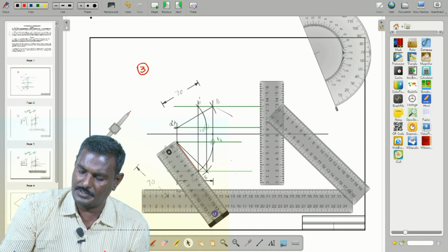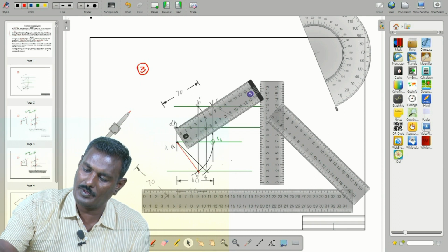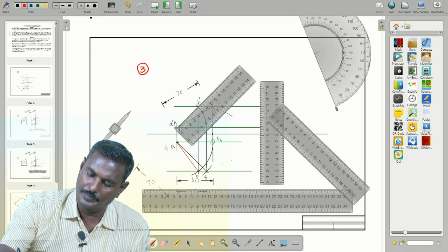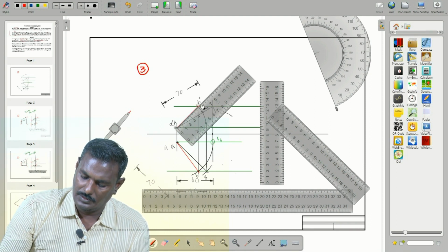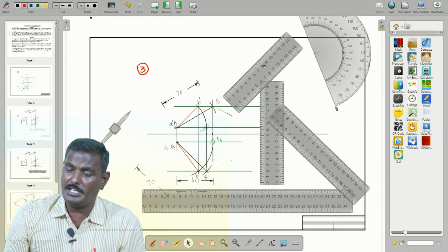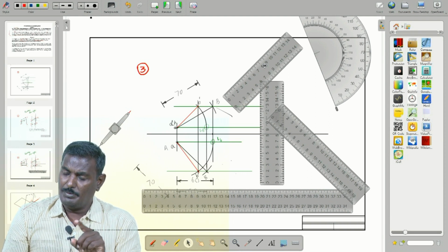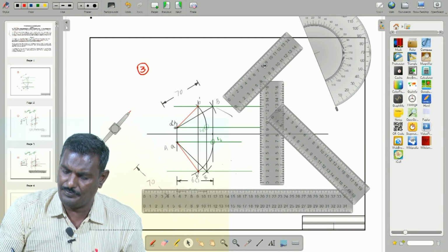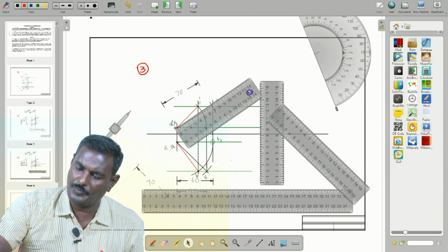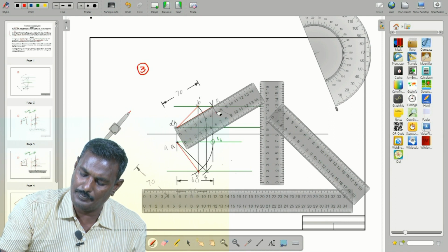In a similar case, from A dash to B dash, draw a line. So, this is A dash, B dash. Also, the true points, capital A, capital B, you have to trace by H pencil as well. That is the final touch up.